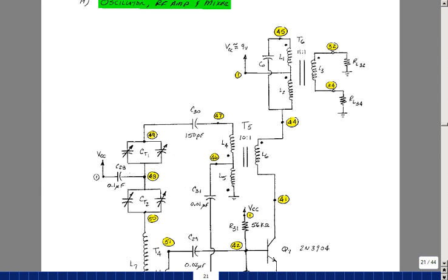So go along into steady state, and then at time t0, which I marked in blue, the current in this coil was a negative number. It was minus 1.71 milliamps if you read it off the curve. I've defined the currents such that they're coming in this direction, going into the dot and then coming out the other side. The same is true for this one, and the same is true for this one. So the current in this direction is negative, so what I really have is a positive current this way of 1.71 milliamps. Likewise, the current in this direction is negative, and it turns out to be 1.45 milliamps.